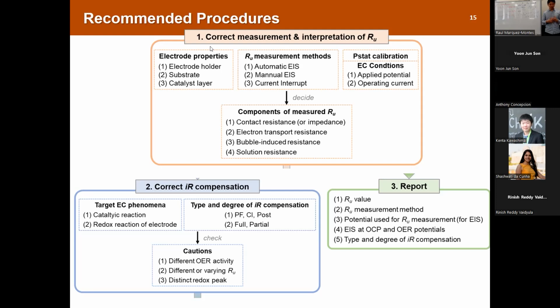Also, if you use a large battery electrode, you will see higher current, which means more IR potential drop. Given that positive feedback mode does not use 100% IR compensation, usually 80 to 90%, you have about 10% error in the IR compensation. When you use a bigger electrode with higher current, your IR potential error is going to be bigger.